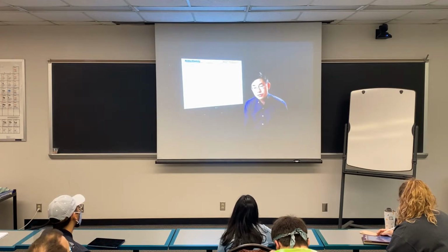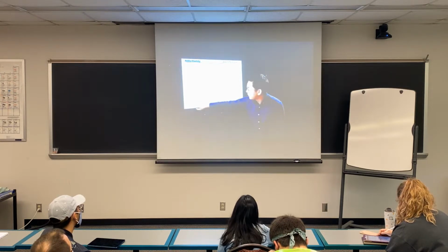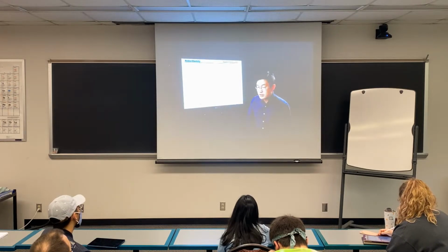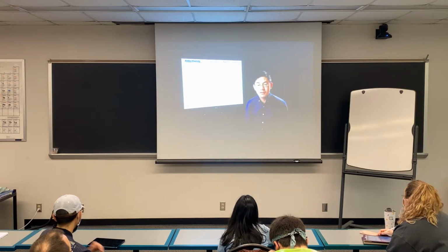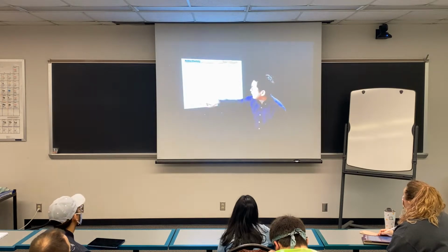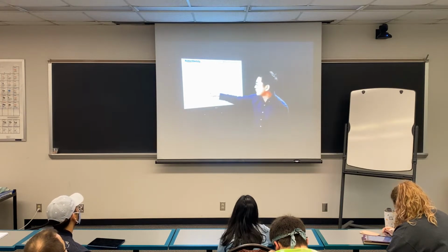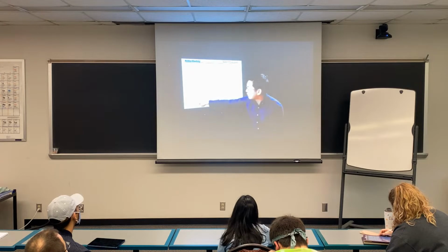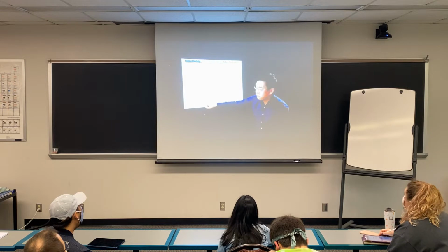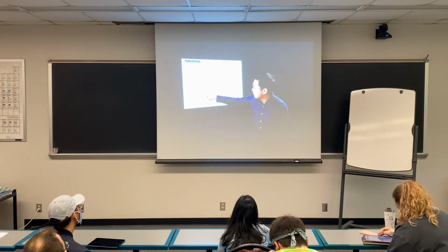This is especially true when you stretch a rubber at very high strain. So look here where you have the extension ratio, basically the draw ratio, from 1 to 8. The higher the extension ratio, the more deformation; 8 means we deform the rubber 8 times its original length, which is a very high value in terms of deformability. You can see that the entropy theory we discussed predicted that your behavior will look like this. But in reality, between roughly 1 to 5 degree of strain, it's pretty much similar, and there is some deviation, but not terribly bad.